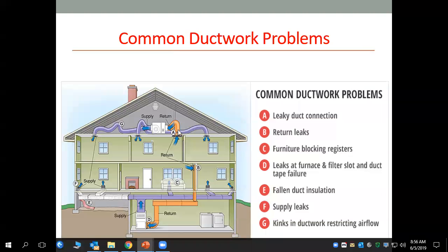Your return air that's coming in is lazy air. Again, my description. It's almost half the velocity of the supply air. And it doesn't care where it gets its air. If there's a big duct there, absolutely I'm going to take the air from there. So it doesn't tend to draw equally from the different ducts on the box, on the plenum.